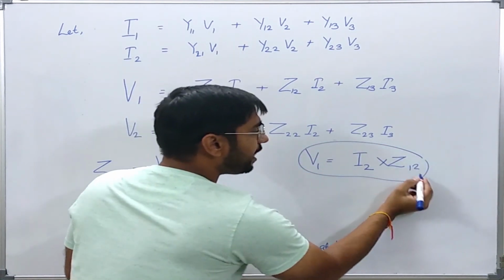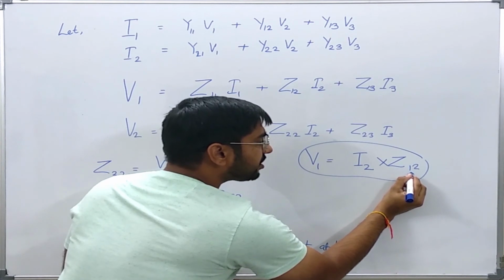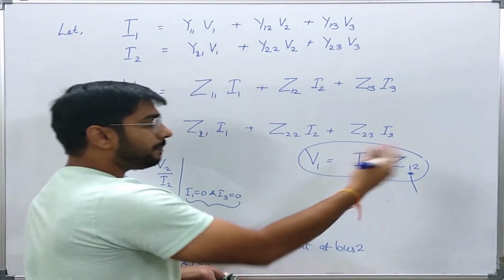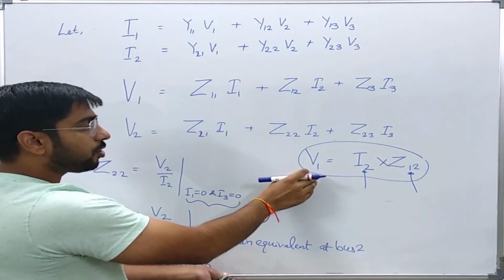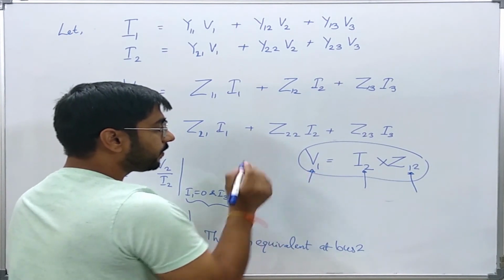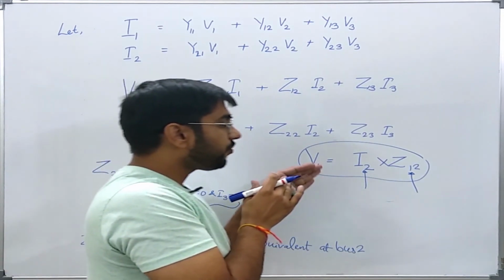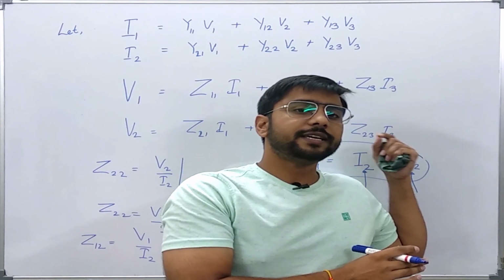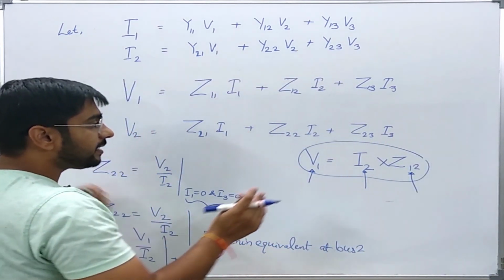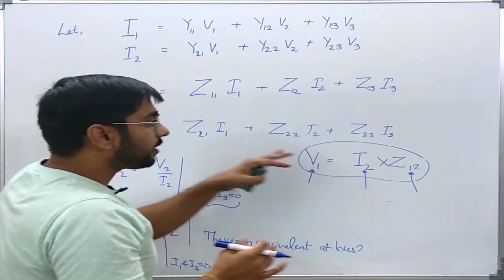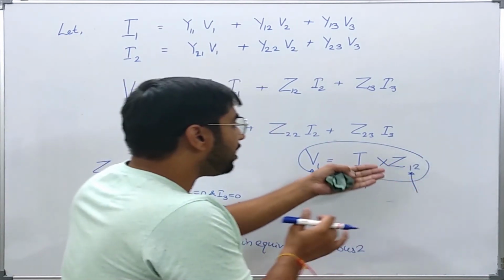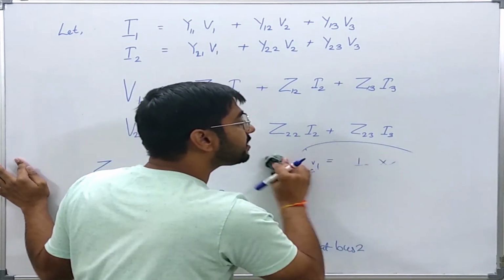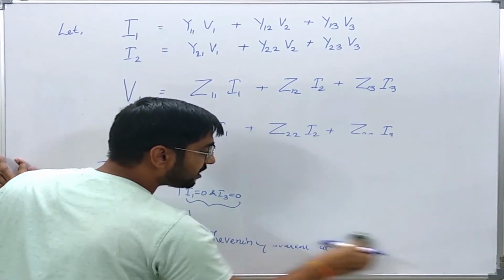So it is some kind of transfer impedance which tries to show the effect of the source current at a given bus, which will give a potential drop or potential at the other bus. Okay, so there is no physical way to show this Z12 as we could have easily shown in the admittance matrix. So you see that the network is not physically realizable just from the given values of the impedance matrix. So these are the major differences in the admittance matrix and the impedance matrix.